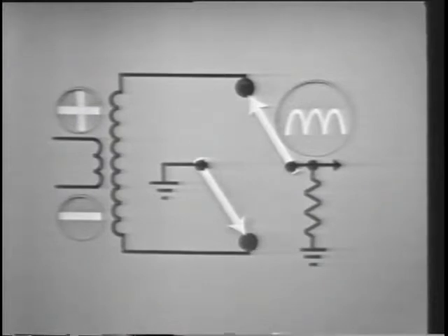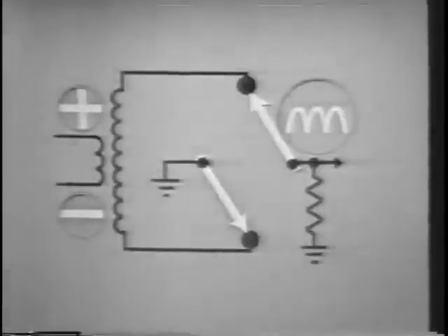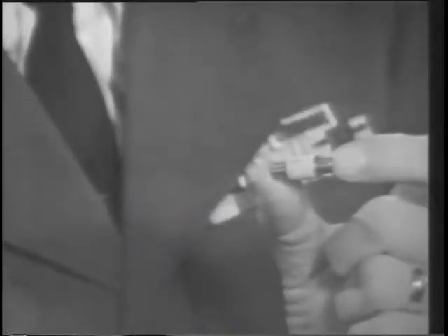Notice that the output voltage is positive. This is because the load is always connected to the positive end of the secondary, and the negative end is always grounded. Of course, a mechanical switch like we used is not suited to the rapid changes of the AC voltage, so an electronic switch is used. The solid-state diode is the electronic switch.